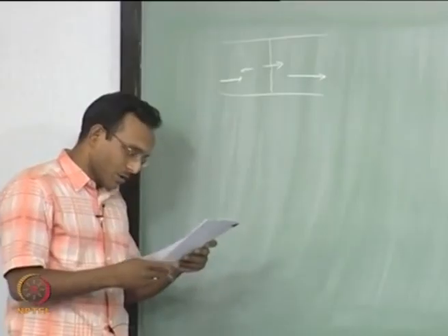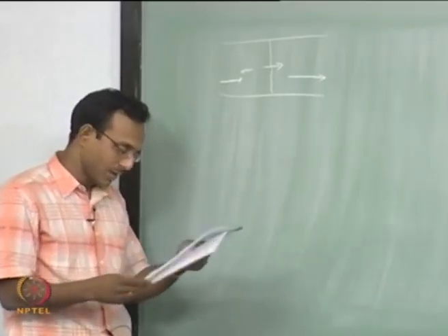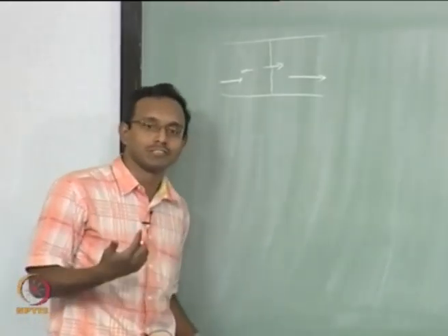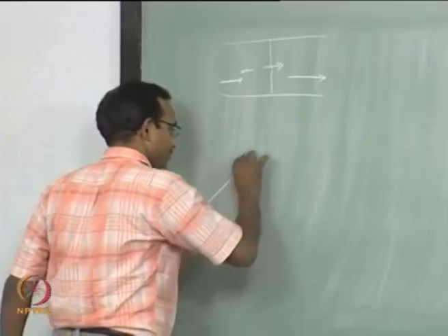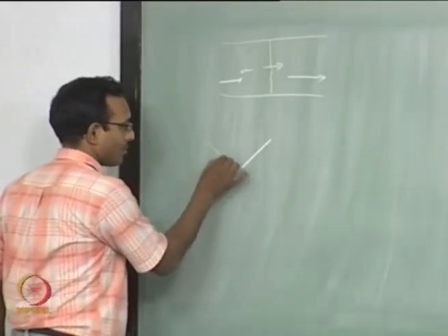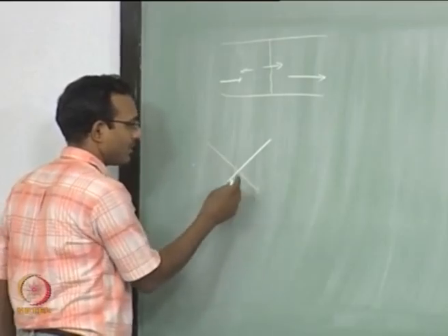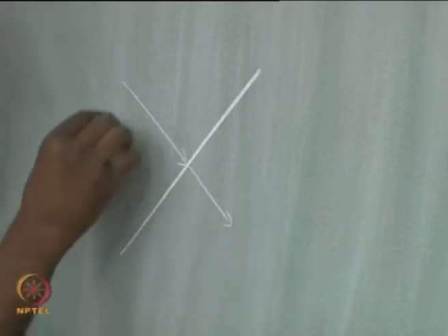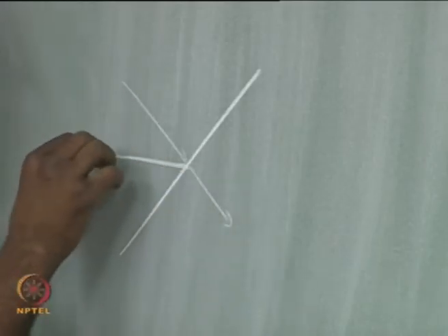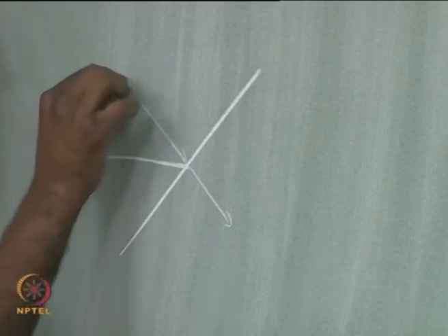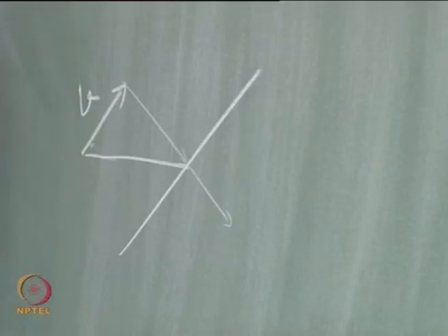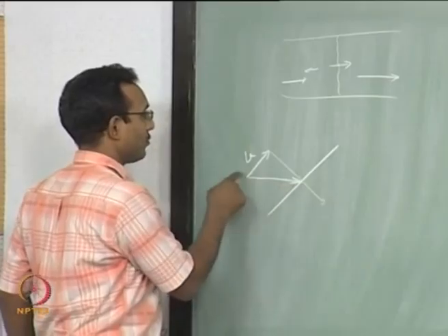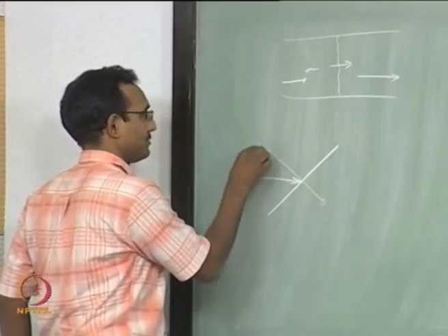Okay. Now we want to derive this in 2 dimensions. We are going to take a similar approach to the oblique shock derivation, where we said if there is a wave, I am going to look at the normal component and how it changes. I am drawing an oblique shock picture here. The arrow lengths are changing that way, and I am going to say that the actual velocity is this, and we have an observer moving along the shock this way, so that with respect to that observer the flow field looks like this.